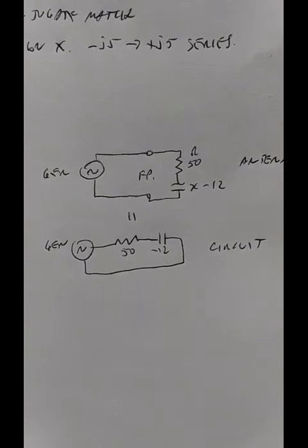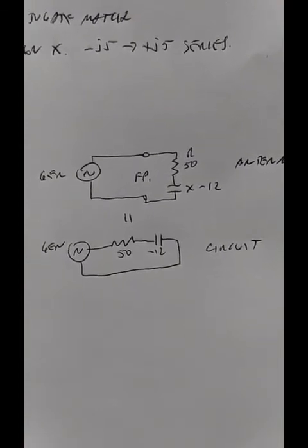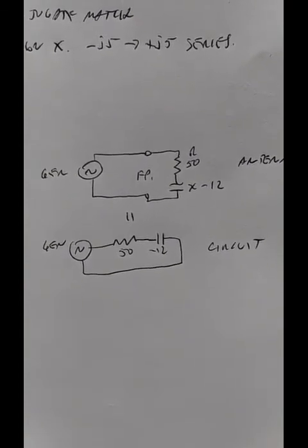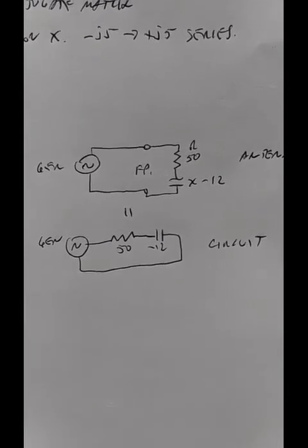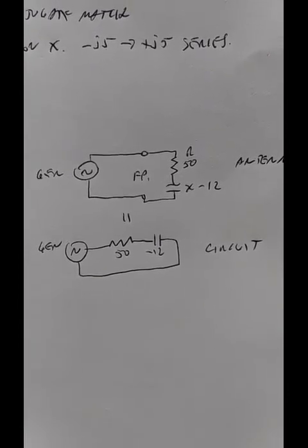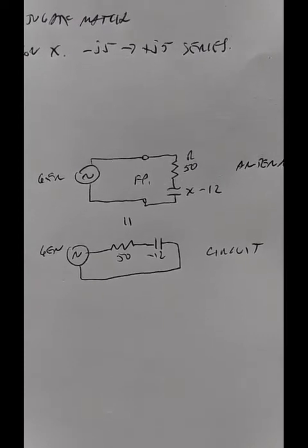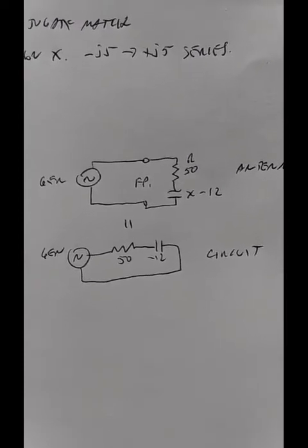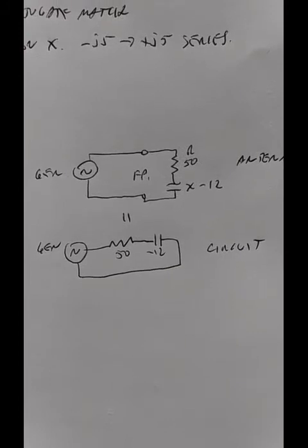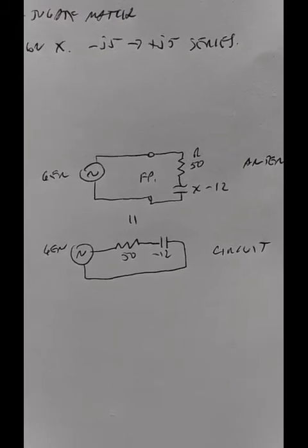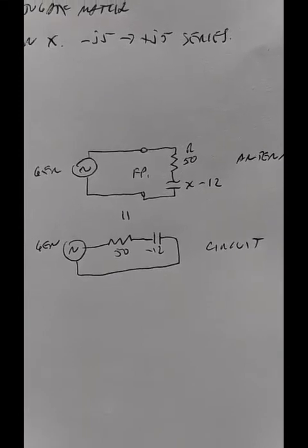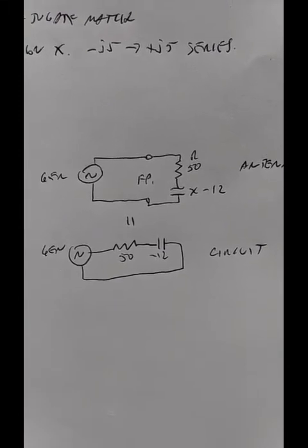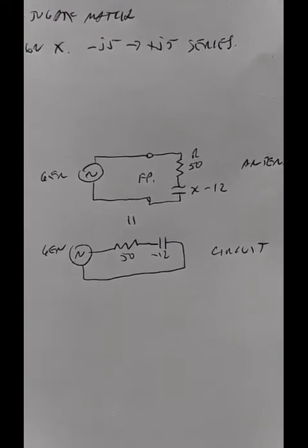And the problem is that X12 is not a real capacitor. That's something with antenna fields, and that portion of the energy is not being emitted because in an antenna, that R value is through the antenna transfer function out into space. The R value is what radiates the energy, and the X is swapped around in fields and either sent back to the feed line or dissipated. It's a loss.